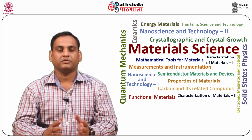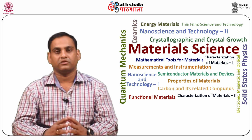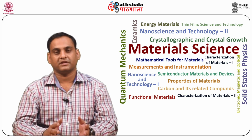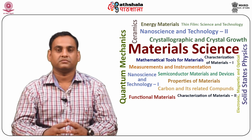Conventional methods of improving the intrinsic and extrinsic soft magnetic properties have been focused on tailoring composition, control of microstructure with heat treatment under different environments, reduction of Hc, that is coercivity, increase of saturation magnetization Ms, and control of intergranular exchange coupling in the amorphous and nanocrystalline materials. Cobalt substituted iron cobalt zirconium boron alloy generally falls under the generic name HITPERM.